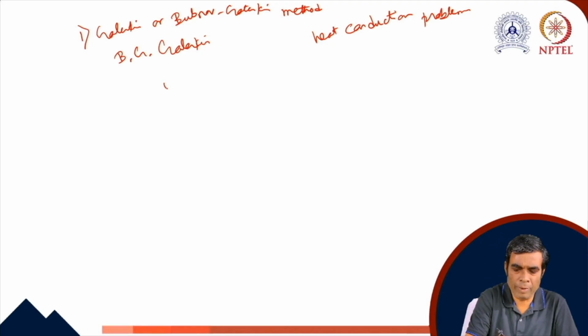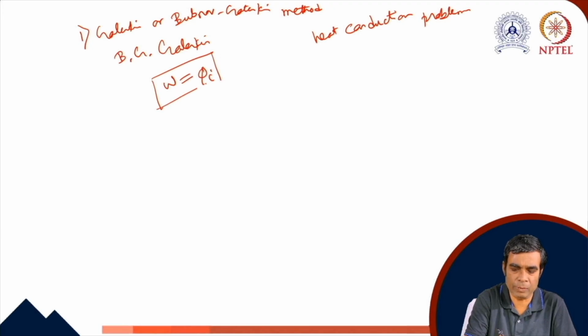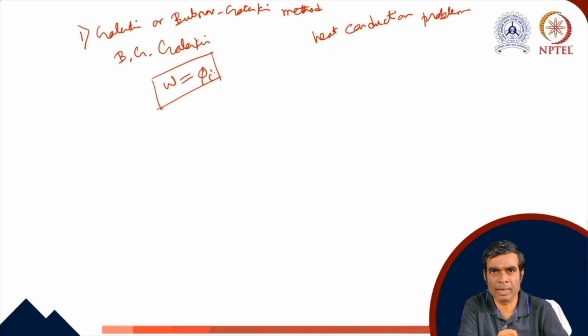But we select the weight function and the approximate function from the same vector space, and because of that we get the same solution under prescribed essential boundary conditions. Okay, so it should be very clearly mentioned that Galerkin method is valid for any kind of problems. We don't use it for conventional fluid mechanics, though, but the Rayleigh-Ritz method is not universally applicable for all kinds of problems.